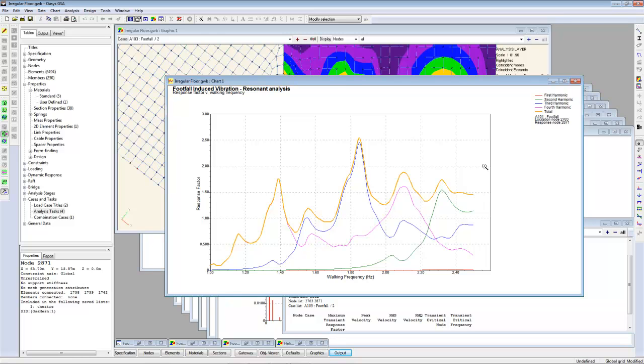And you can see the general analysis, which is up to 2.5 Hz. The peak response is actually coming from somebody walking at about 1.85 Hertz. But you can see you do get peaks at particular points, and sometimes reducing the maximum walking speed doesn't actually reduce your response values, because it might not be the highest walking speed which is actually governing the results there.